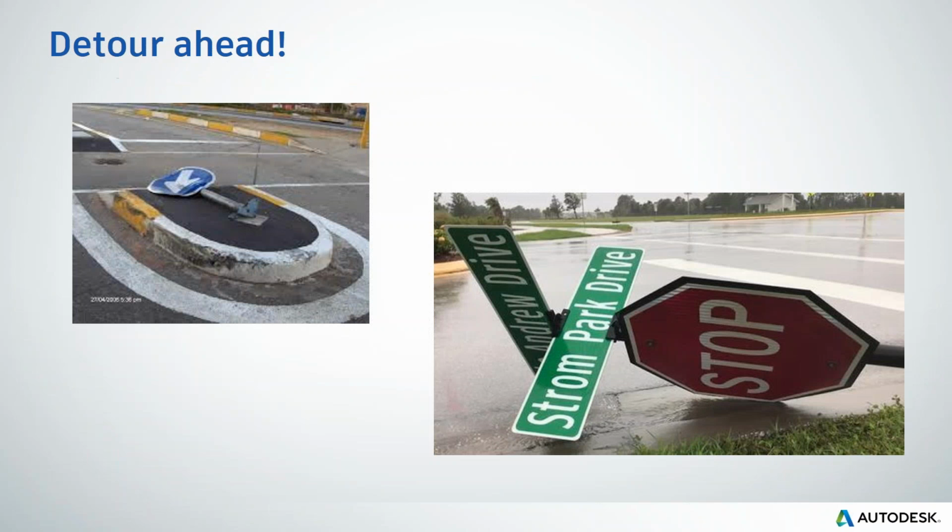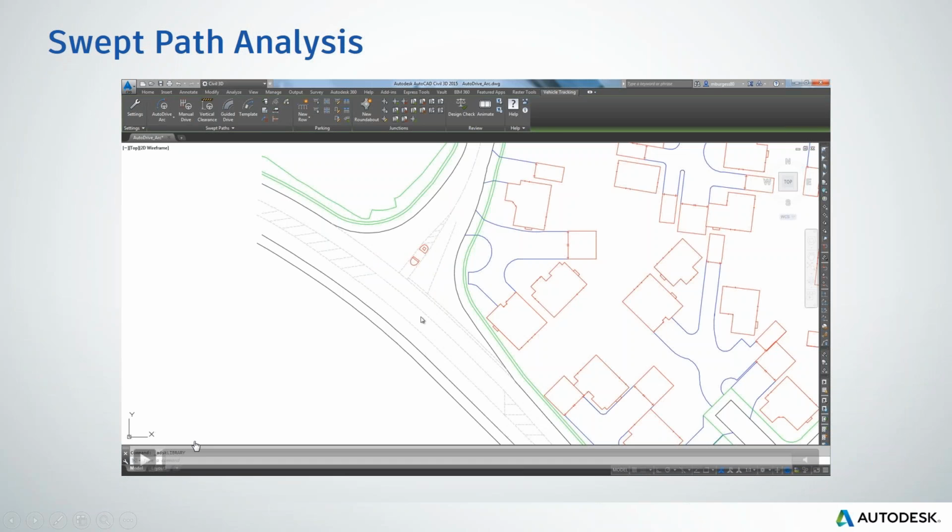We saw traffic analysis. And what about sweep path? So if you have incorrect sweep path and you are sending big vehicles somewhere where they are not really capable of turning, here can be the result. So basically the traffic signs can be destroyed, etc. So and cars and so on and so forth. So with that, what I believe is also important to check is sweep path analysis.